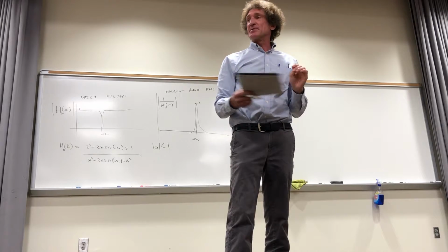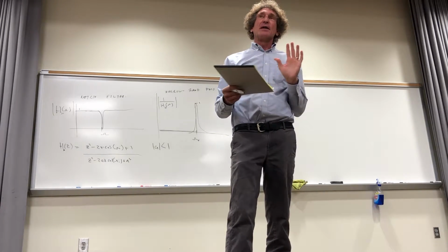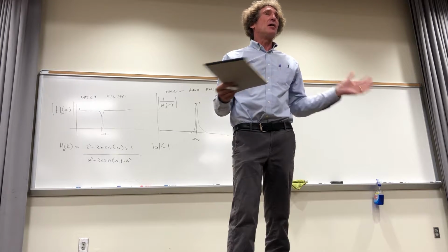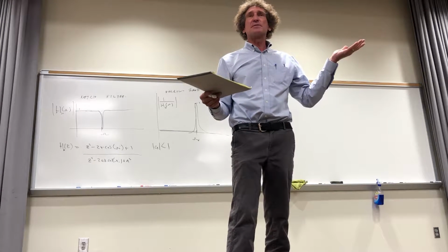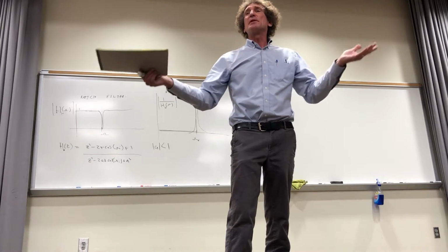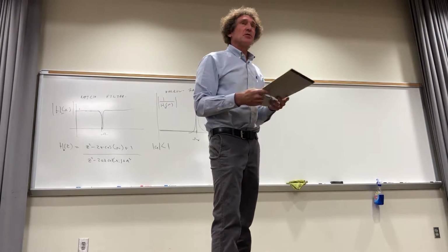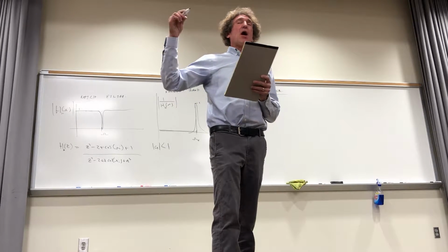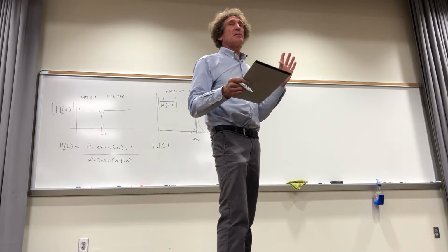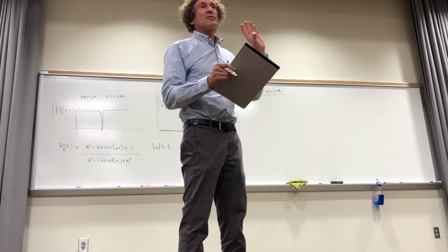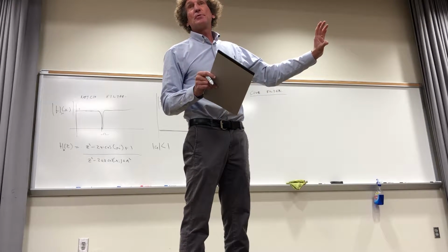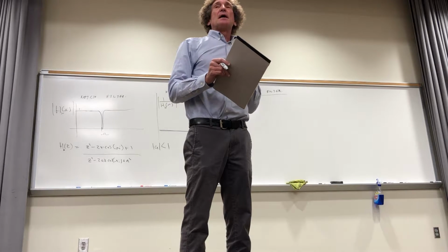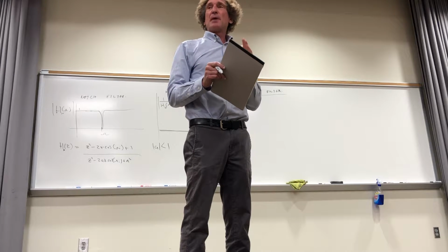There's an evil menace called 60 hertz out there. Now, has anybody ever had any kind of 60 hertz hum in anything? You know what I'm talking about? You have? Does anybody else? It's the most annoying thing, and it's everywhere. Not only is 60 hertz there, but all its harmonics. 120 hertz, 180 hertz. All these other harmonics, anytime you have anything that takes that and rectifies that and makes it into a DC signal, you get these other harmonics that are all over the place. And it is just a pain in the butt.